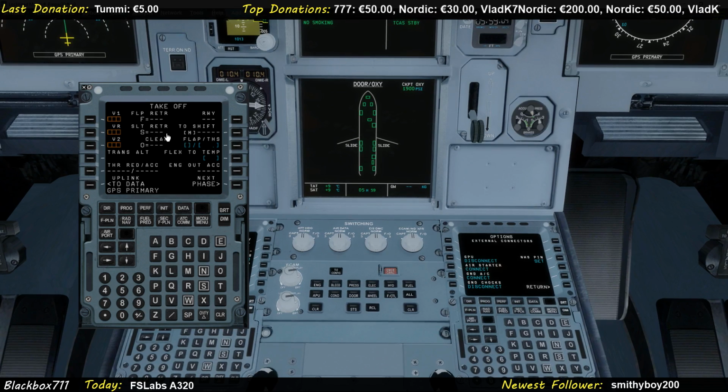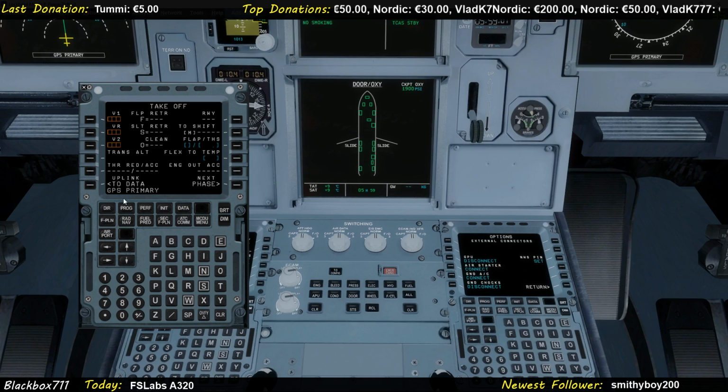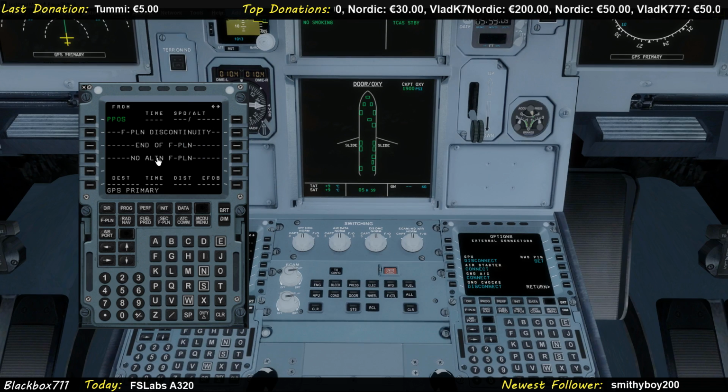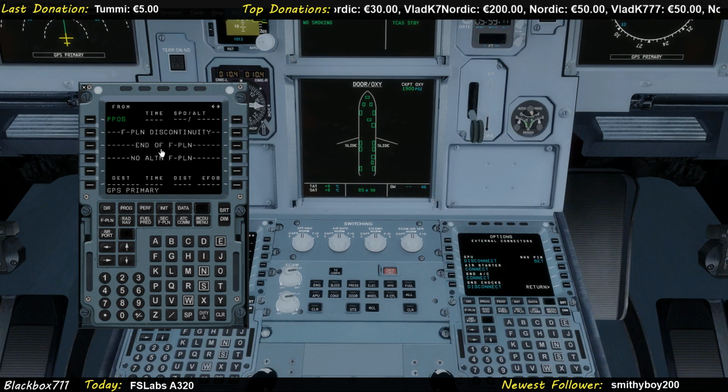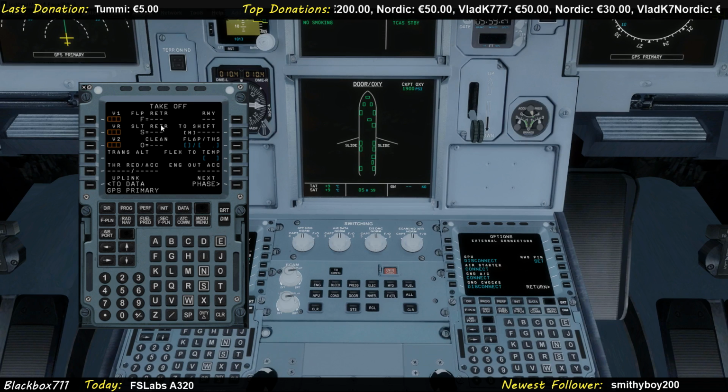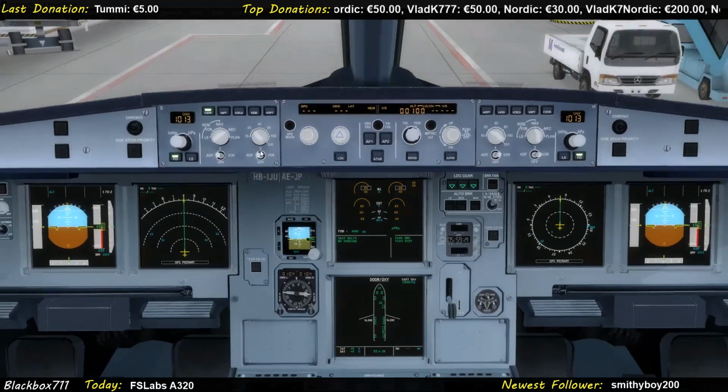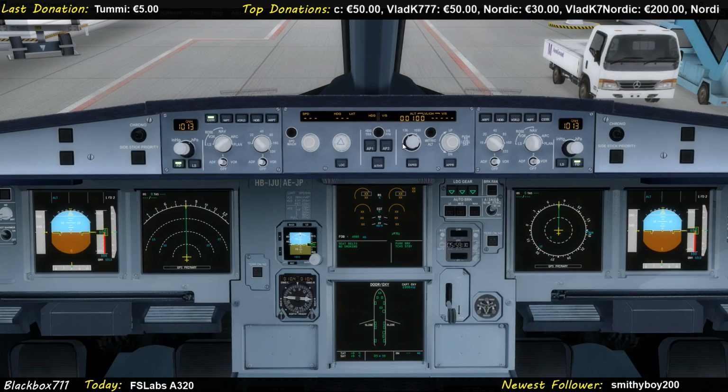The MCDU will put that data towards the computer, and the flight management guidance computer will then manage the climb, the descent, the cruise flight, the approach, and so on. All different flight phases are optimized by the interaction through the MCDU. For short-term interactions, you would use the flight control unit.